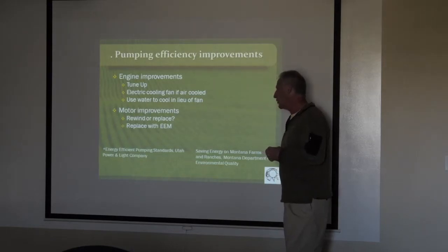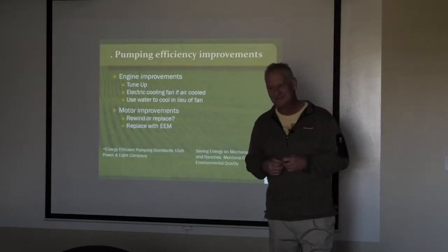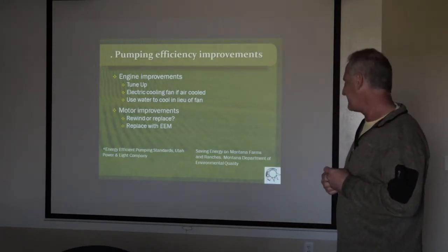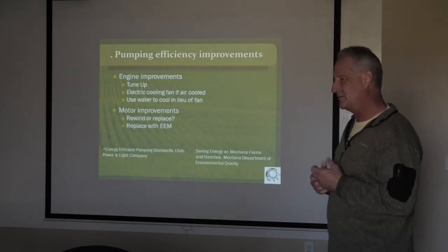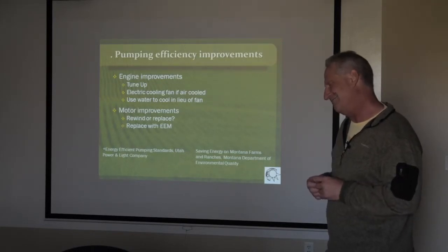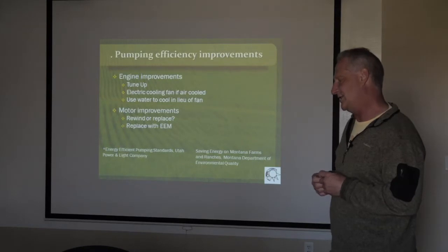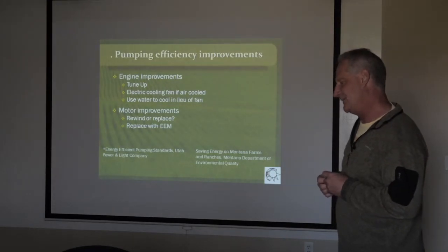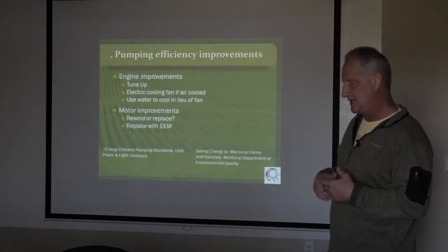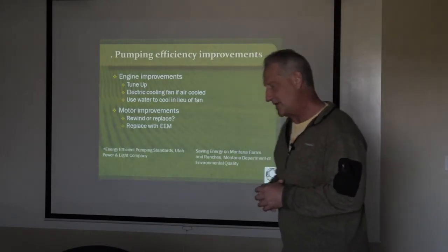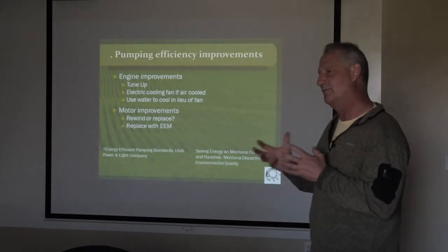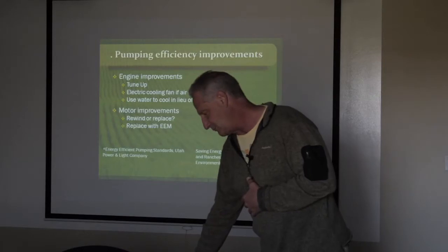Motor improvements, rewind or replace. The cost effectiveness of replacing a motor with the same size has a long payback because they're pretty efficient to start out, so it's not a really good energy saving measure. But if the motor has failed and you're giving people advice, you can say replace it with an energy efficient motor, because they have a higher standard. They're more expensive, but the difference in cost pays for itself pretty quickly.